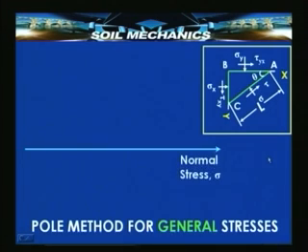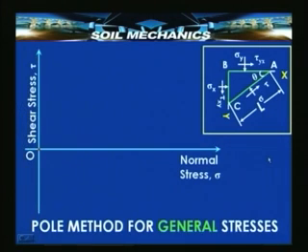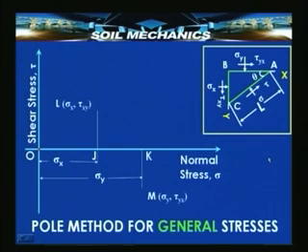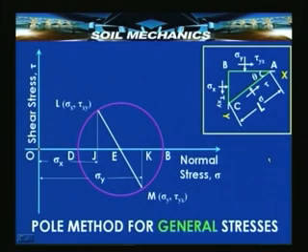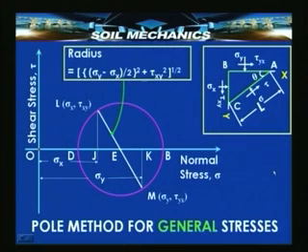First, draw the normal stress axis, choose the origin and plot the vertical axis, plot sigma x, find out the points J and L, plot sigma y, find the points K and M, join LM, get E, draw a Mohr circle, get the points D and B. The radius will be given by this expression.